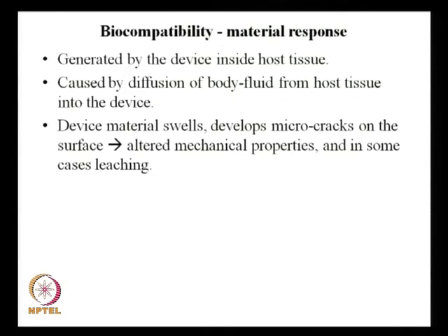One is the response that is given by the material itself. That means, you insert a microstructure device inside the human body. Now, that material will respond in a certain way. You have to ensure that the material remains intact, the material does not erode or swell. So, that is important. The other issue is the cellular response. The cells around that material, the human body, should not get destroyed.